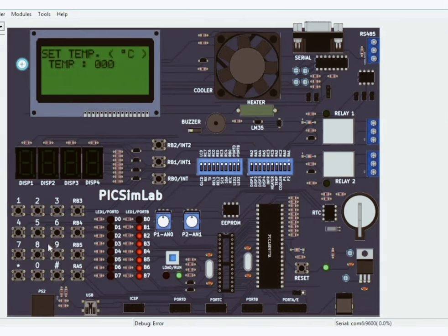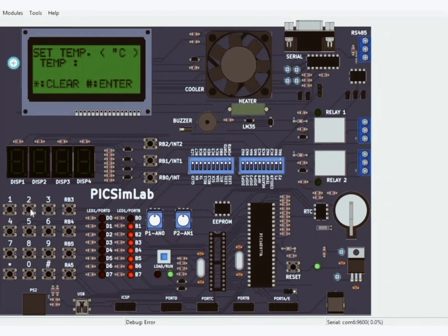It's showing that to enter a valid temperature. As the temperature we pressed was 275 degrees Celsius, which is more than 255 degrees Celsius, the buzzer sound became on, indicating to enter a valid number. Now I will press a valid number, that is below 255 degrees Celsius. Let us set 125 degrees Celsius. I am going to start by pressing hash. The preheating has started. Here the preheating temperature we can see is 180 degrees Celsius.